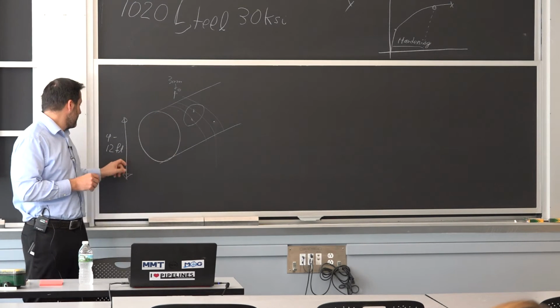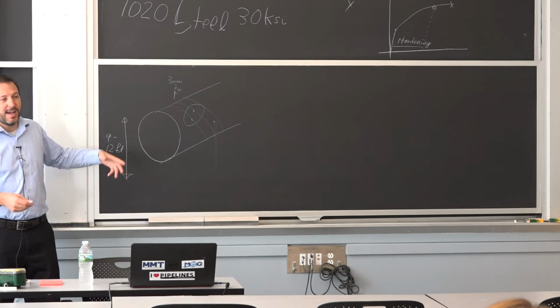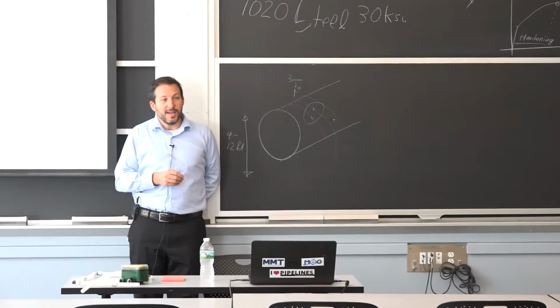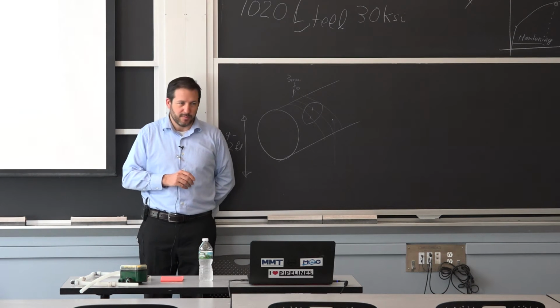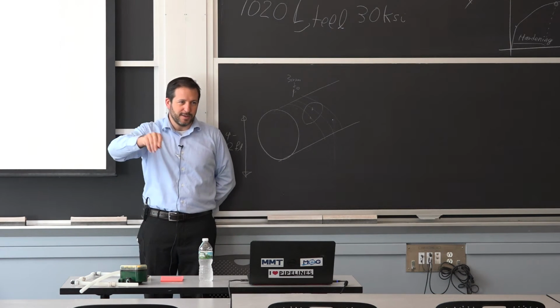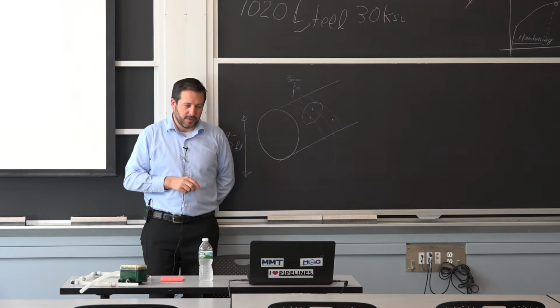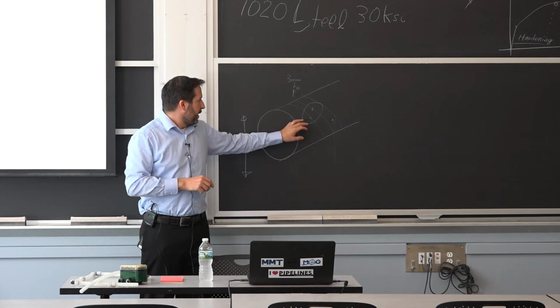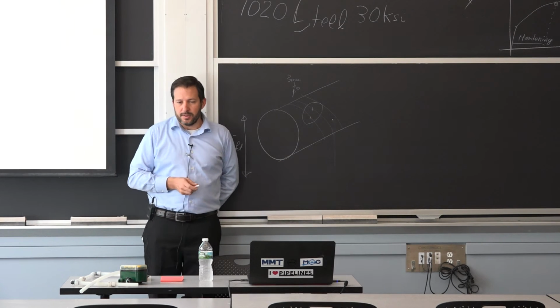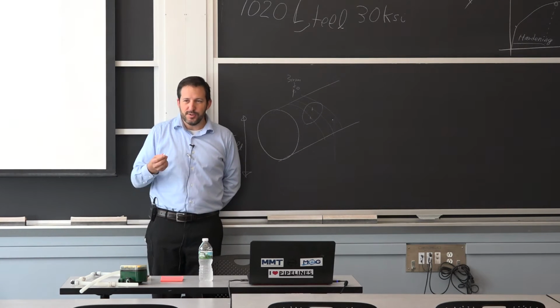If you try to make a 12-foot diameter cast iron or steel pipe, it's going to be extremely expensive, and it will also have some variation in it. There'll be some welding here and there, and it's not going to be perfect. So the idea here is they put a monitoring system, and this one is actually very nice because you can use acoustic emission.